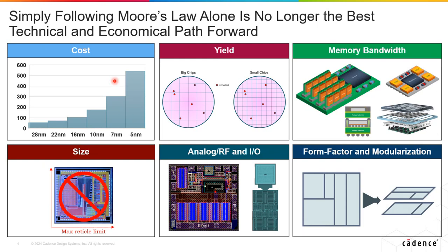Another factor is that large electrical-size chips typically don't yield very well compared to smaller chips, and of course low yield means higher costs. We saw an example of this with Xilinx around 2008, when they partitioned a large FPGA into four small, high-yielding chips and connected the four chips together on a silicon interposer, arguably launching the 2.5D IC packaging trend that has become commonplace today for HBM processor integration.